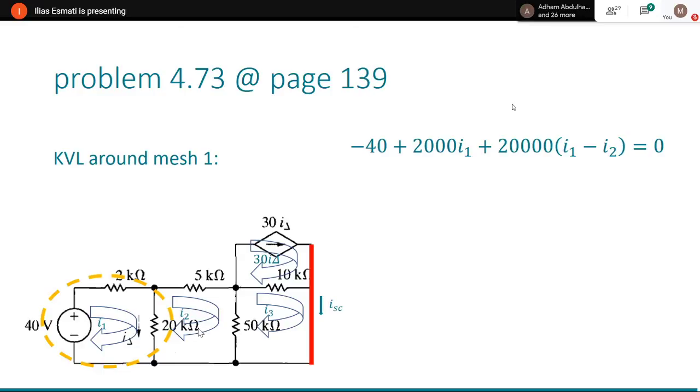Since there's also current going, if you can see my mouse, I2 is going in this direction, against I1, and I1 is going clockwise. I2 is going counterclockwise at this meeting point. That's why I need to take I2 out of it, so I subtract that one. And I let everything equal 0. Why? It was what Kirchhoff taught us, Kirchhoff's voltage law.